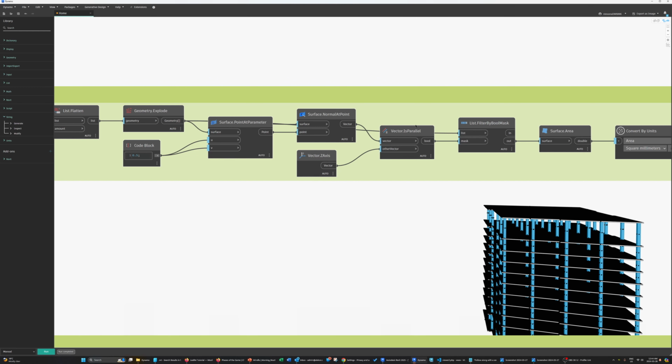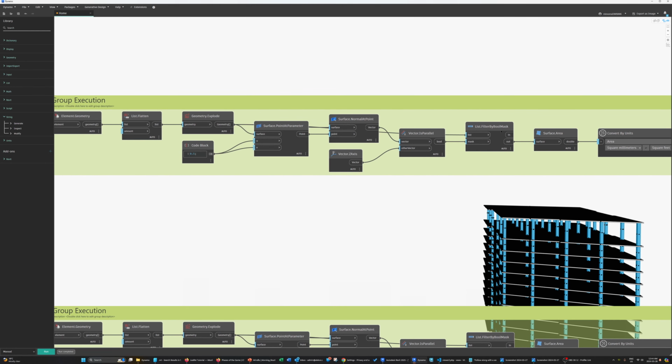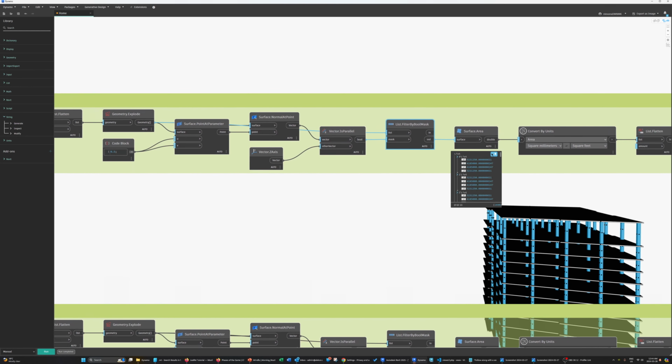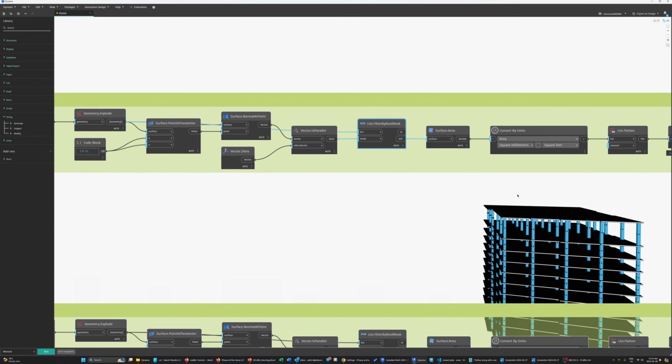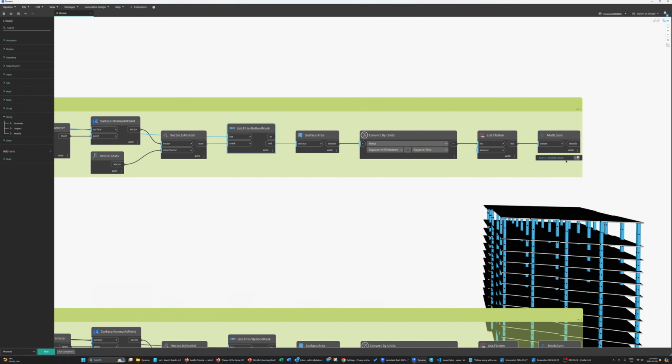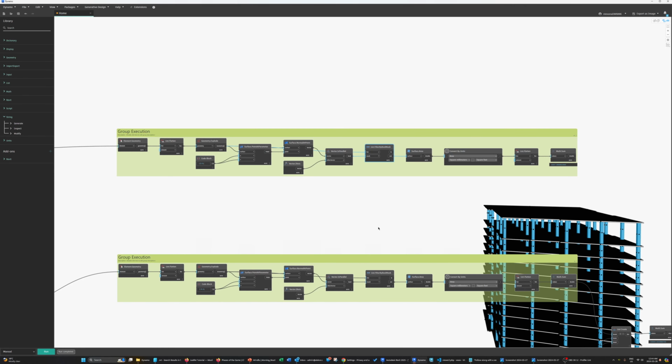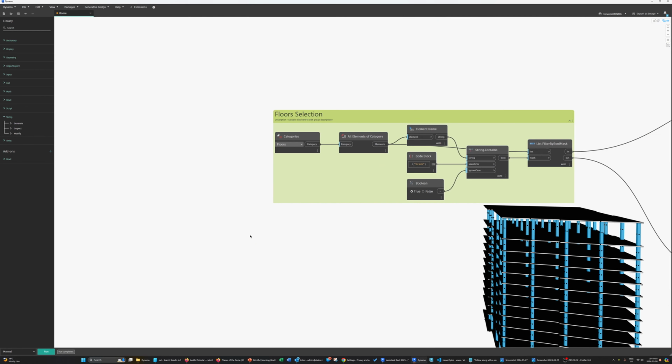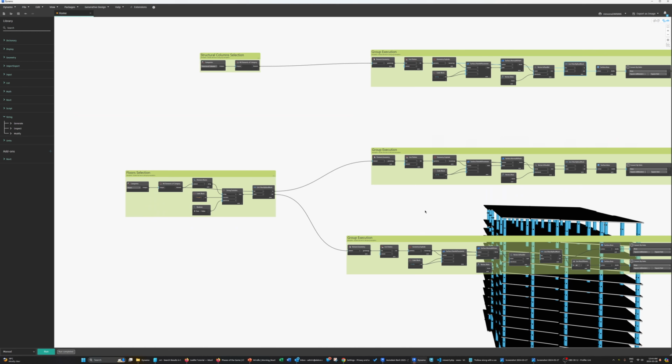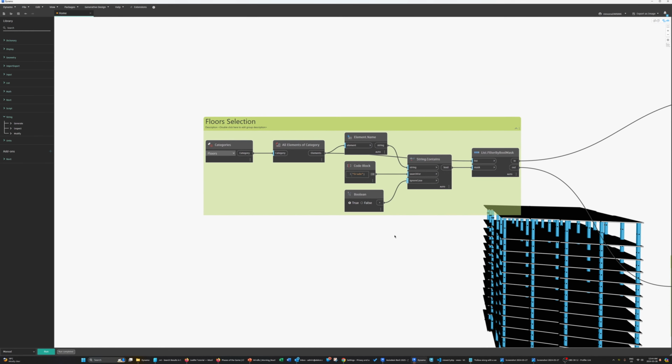Lastly, we're going to look at the z-axis. Is it parallel to it? If we have something that's vertical, even if we have a z-axis anywhere else, it's going to be parallel. Going downwards or upwards, it doesn't matter. We get a bunch of trues or falses. This way we can filter our surfaces and get the proper ones to look at the area, convert the units, and then flatten that list and sum these results up to get a proper number. To scale this into other categories, we're just copying and pasting, and modifying some of these components. For the floor specifically, we have two types of floors.